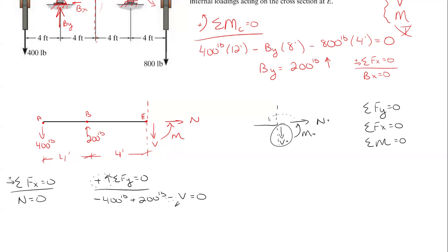When V comes out with a value, if it is in fact a downward value, that is considered to be positive shear. The positive sign notations for internal forces are not in conjunction with these. These are totally different. These are which you're using positive and negatives inside the summation equation. And this will make a lot more sense once we get through the problem here. I just wanted to point that out as we go along because I've gotten that question before.